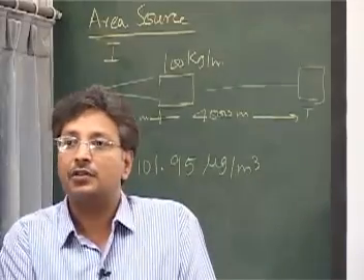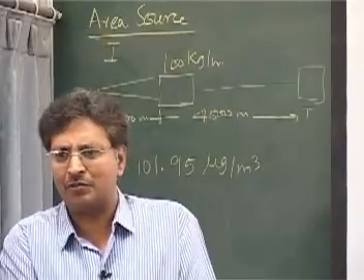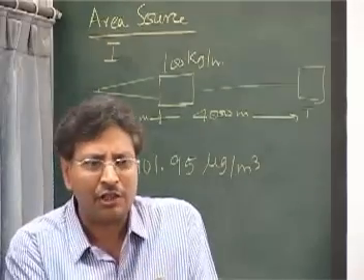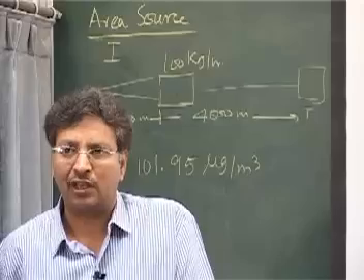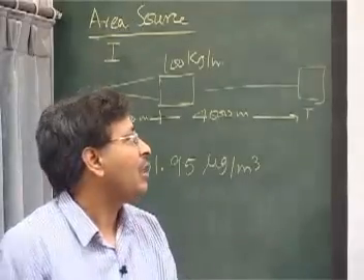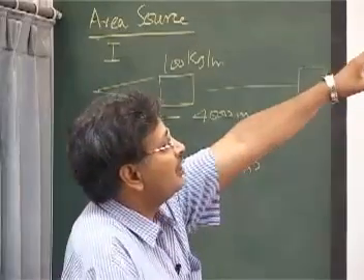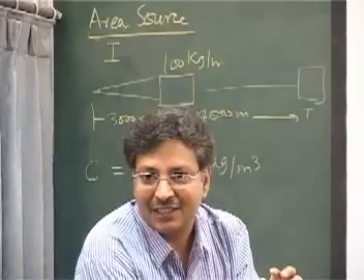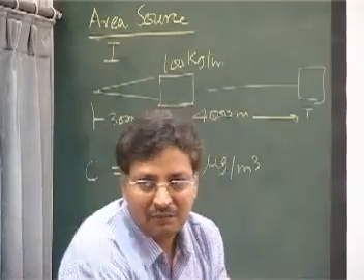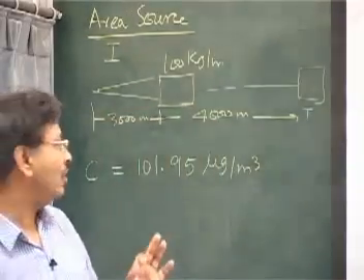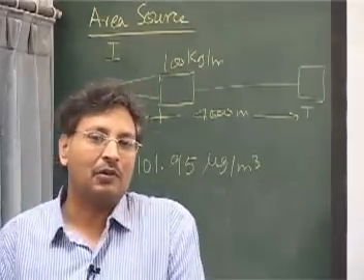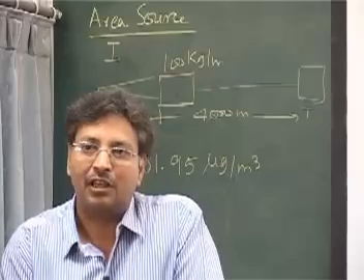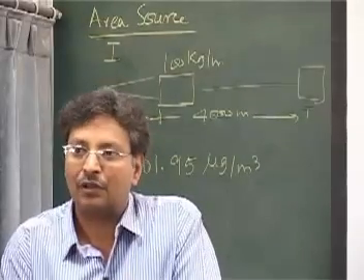I can assume this to be nearly 50% of source 1, because concentration is always proportional to Q. H is more or less the same, and the difference you will see is the difference of 1 kilometer distance, right? That will have some impact, but if we agree to save time, we can say it's 50% of area source 1, because Q is 50%.